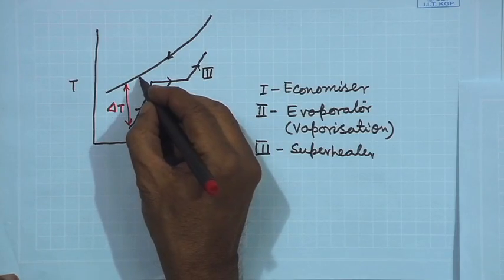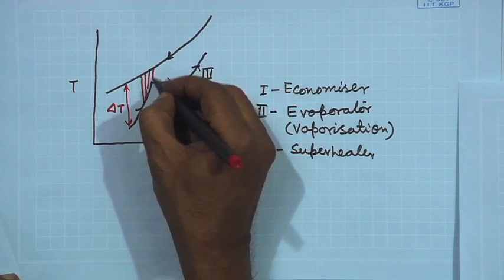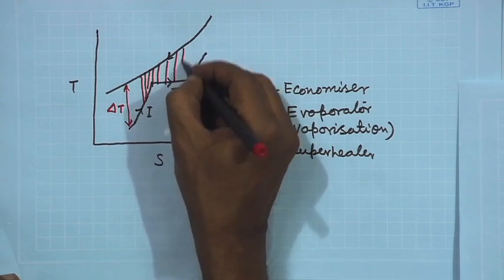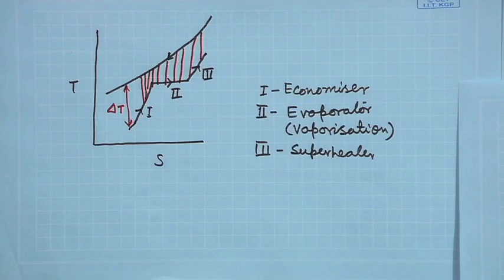The thermodynamic advantage is that, let us say this heating is done internally by cycle modification, then external heating is from somewhere here, and external heating, you see, I am doing at high temperature. Heat addition at high temperature is beneficial. That is why I have discussed this point also earlier.